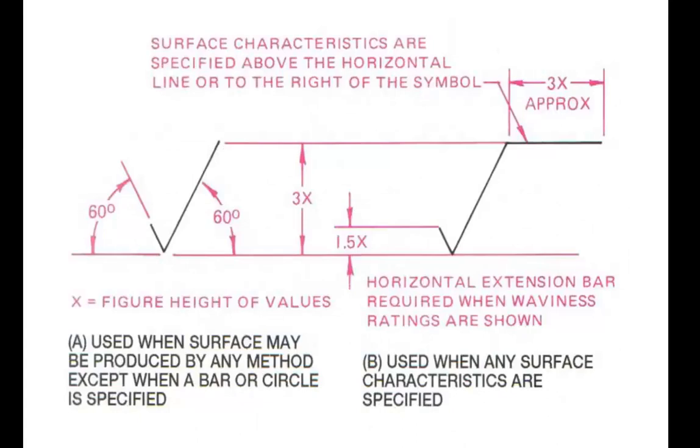The standard fully describes the size and shape of the surface finishing symbol. Today, CAD software, by its configuration, can inherently satisfy the format requirements. The surface finishing symbol, its shorter leg, its longer leg, and its shoulder, are to be in such a size. Inclination 60 degrees.